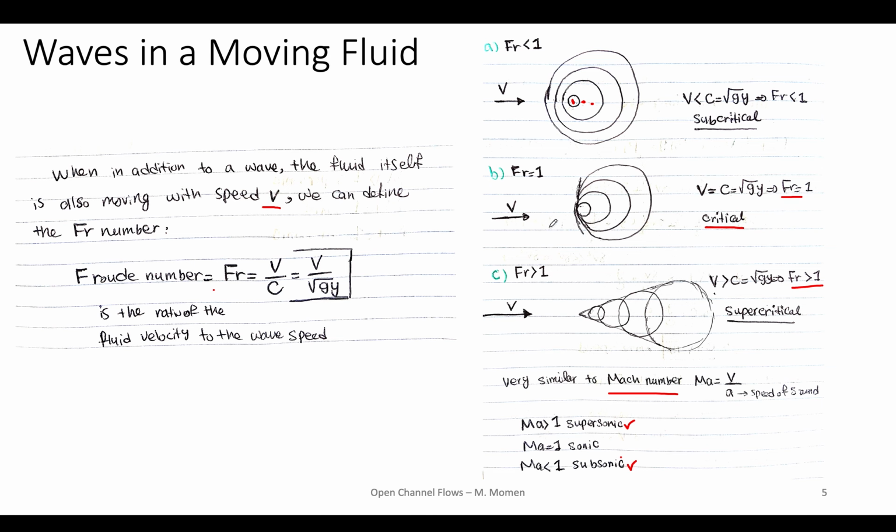So this was kind of an overview of the Froude number, because this is very important in the hydraulic engineering context, where flows are going to change from supercritical systems to subcritical, and vice versa, depending on the width of the channel and also the velocity of the channel and other phenomena that we're going to go through in the next sessions.